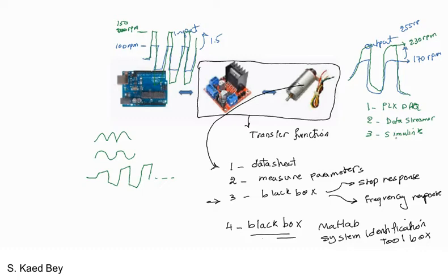In order to use Simulink, you have to download the Simulink support package for Arduino hardware, where you can simply upload a Simulink block diagram directly to your Arduino, where it will be able to communicate with your inputs. So it will stream your data straight away to the Matlab workspace environment.